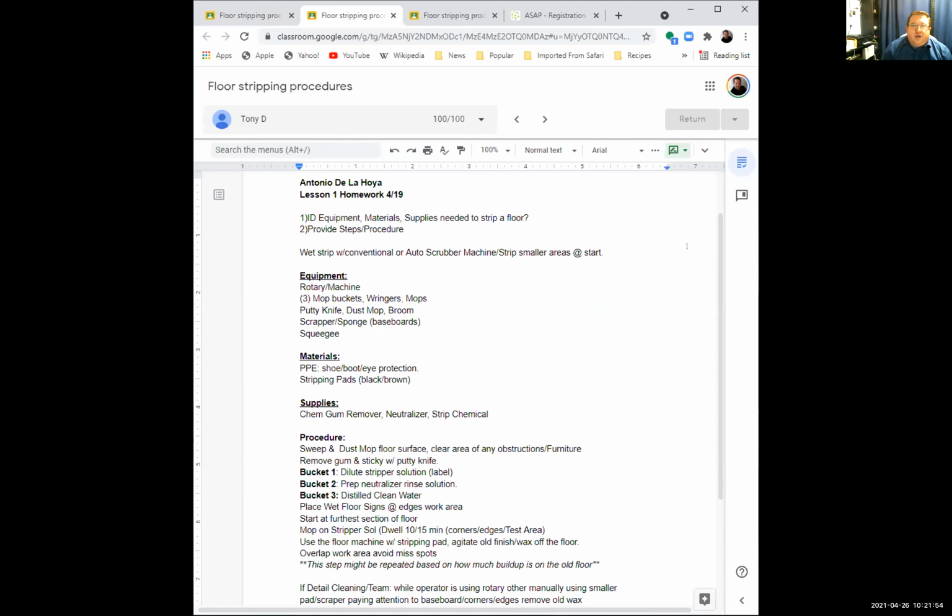Here's the other area that it's going to improve on. You guys saw how much time it takes for floor finish to dry. We were drying in about 20 to 30 minutes easily. If we were doing a multi-purpose room, and let's just use that 3,000 square feet, by the time I get from the area I started laying finish to the area that I walk out and finish, where I started is possibly close to dry already.